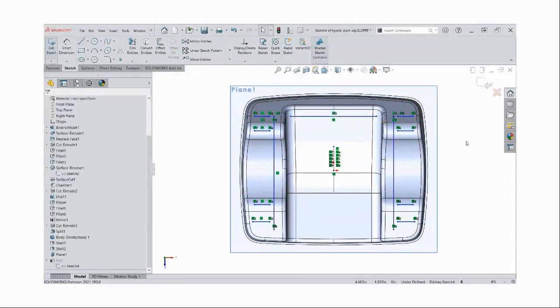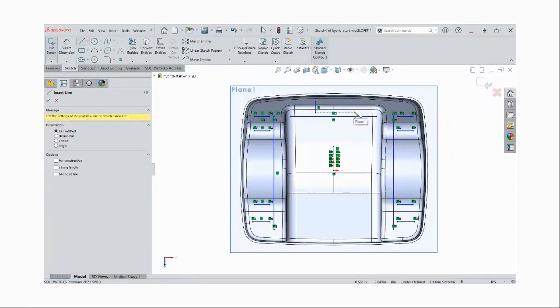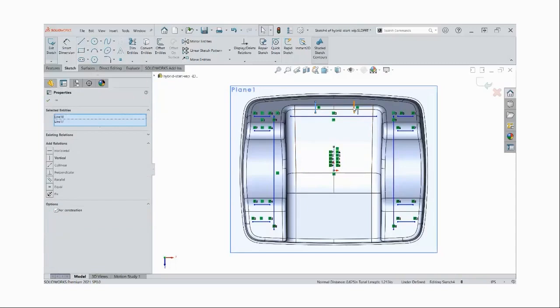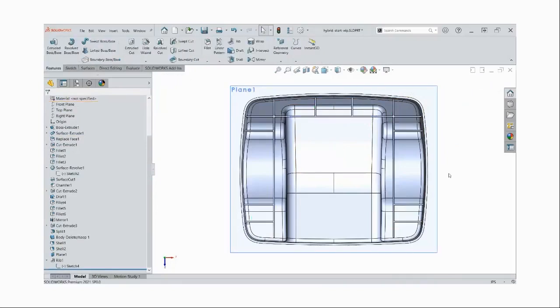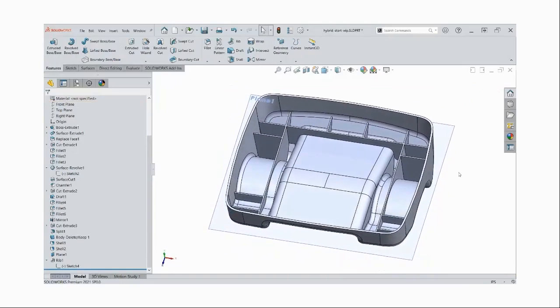have like a little one in the back and some little vertical ribs, just to kind of show how much you can load into just the rib command. It's pretty powerful. There are fallbacks for it. If it doesn't work for what you wanted, then you could always do like a thin extrude and do some more manual manipulation, but you can create some pretty complex rib patterns. They don't have to be 90 degrees to each other like this either. They can be circular arcs and all kinds of funky patterns that you want to be using.